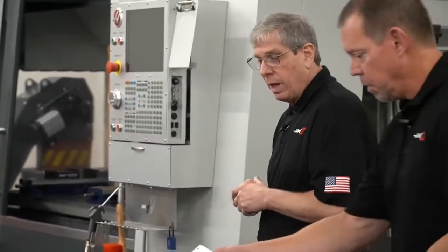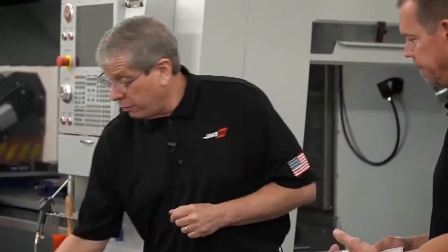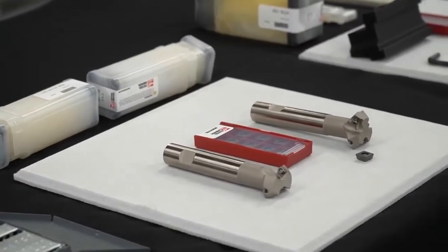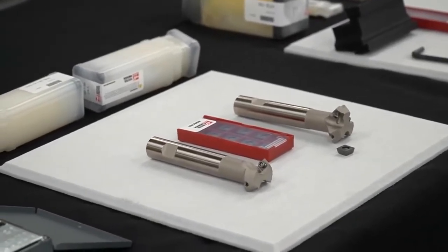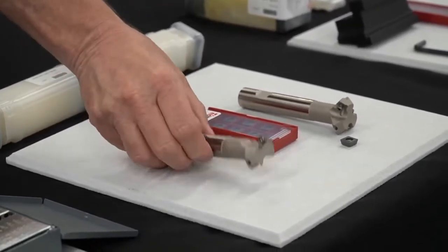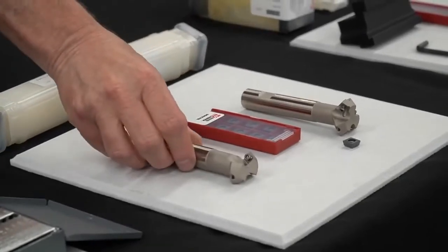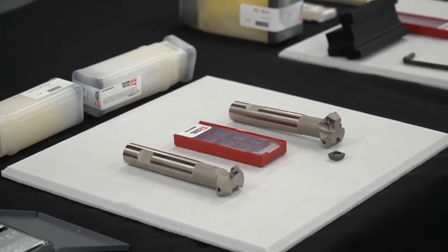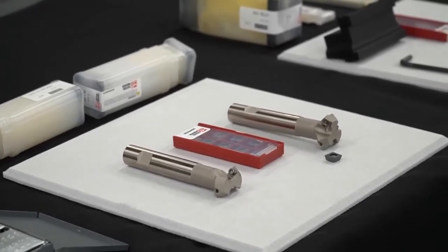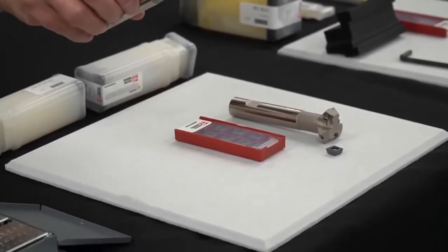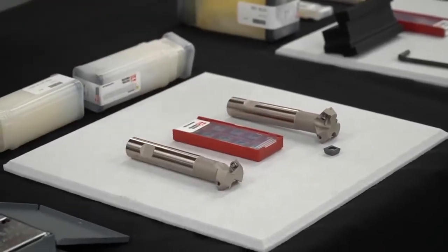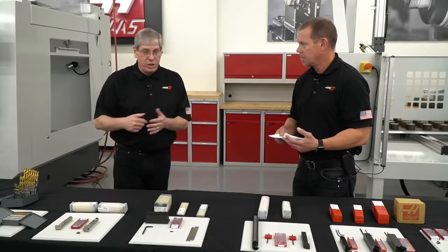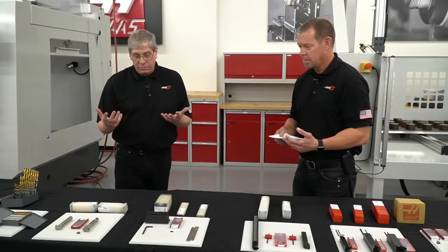Okay, moving on, a couple of chamfer mills, inserted mills. Every good machine shop takes all the sharp edges off of the part in the CNC machine before the part comes off. So these are fantastic. There's a 2-flute and a 3-flute version of the chamfer tool. These are great for obviously chamfering the top edge of a part, but with the relief angle on the shank, you can get to the bottom and chamfer the bottom edge of a part before it comes off the machine.